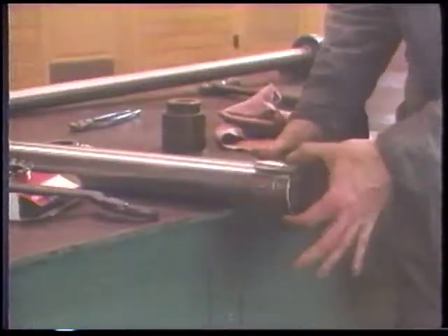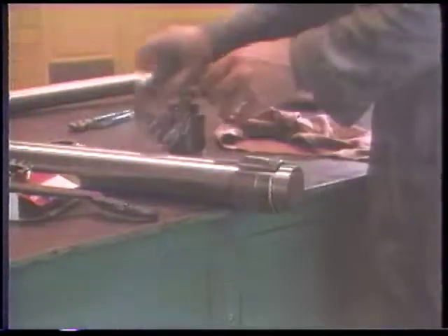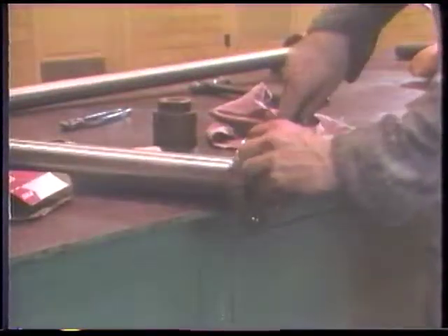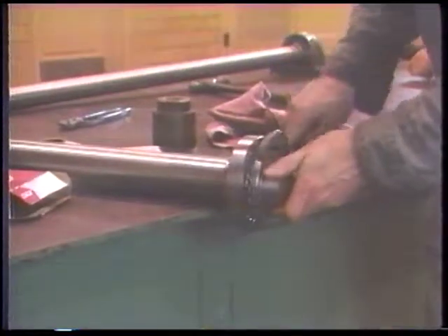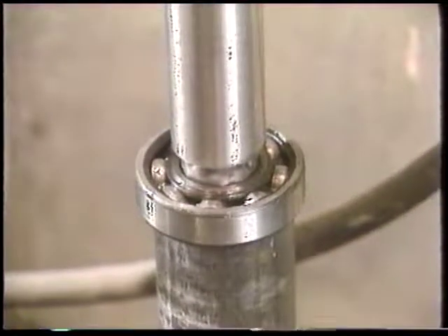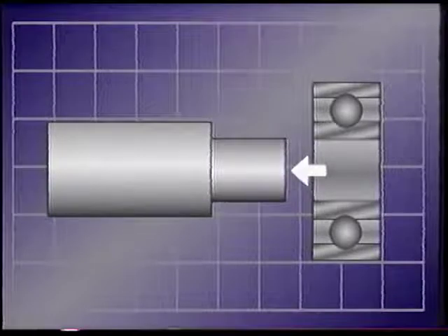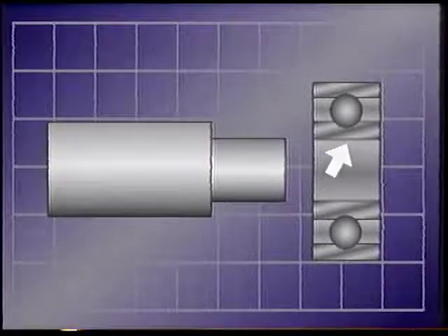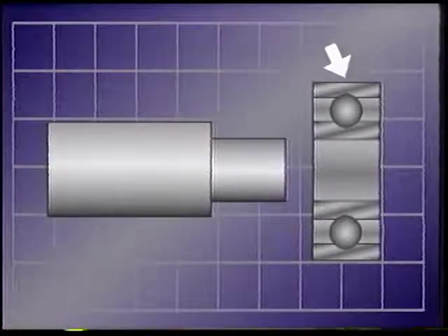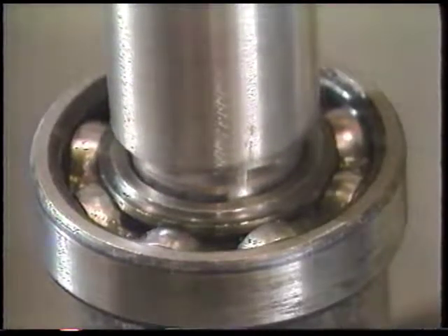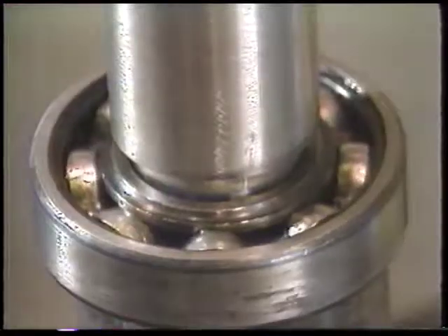Large bearings often use a tapered adapter sleeve. The tightness of the fit is adjustable with the nut, which forces the bearing inner ring tight on the tapered sleeve. Press fitting is another common way of locking a bearing ring in position. The shaft is supplied slightly larger than the bearing's inner ring, or the bore is made slightly smaller than the bearing's outer ring. Press fitting a rolling element bearing puts very high forces and stresses on the bearing.